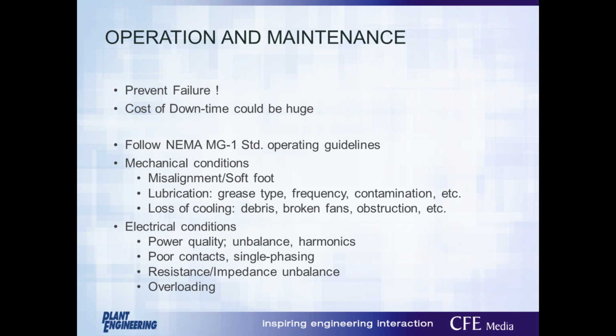You can also use an ammeter to verify amperage at the motor leads if you have access to those. Once you have the amperage readings, you can compare to the motor nameplate full load amperage. Additionally, with the motor de-energized, you can check winding resistance of the motor. The motor should have balanced phase-to-phase resistances.